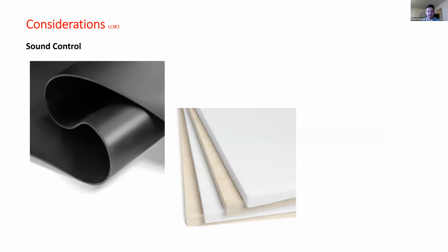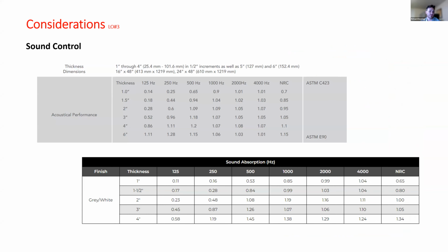In the realm of sound control, you have materials like sound absorbing panels and mass loaded vinyl. These help minimize unwanted sound transmission, which creates a comfortable acoustic environment. The sound absorbing materials can reduce noise levels almost completely, which significantly enhances the usability of the space. Effective sound control requires strategic use of materials. Mass-loaded materials, for instance, offer flexibility, and the higher mass results in better damping of noise. This approach is particularly effective in multi-unit buildings where sound privacy is a concern.